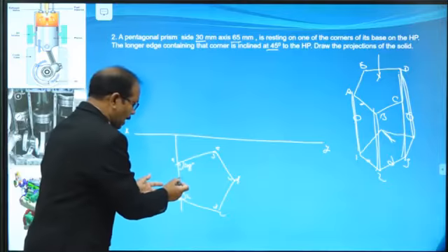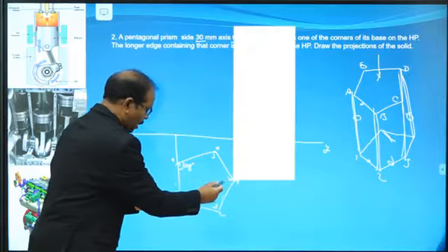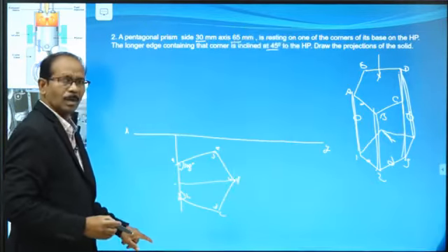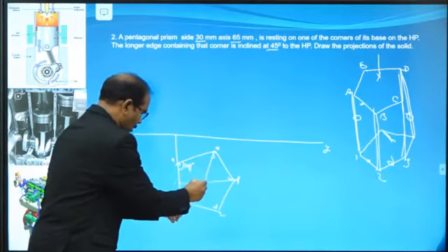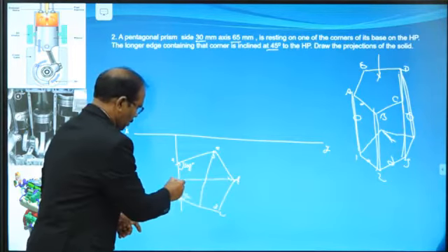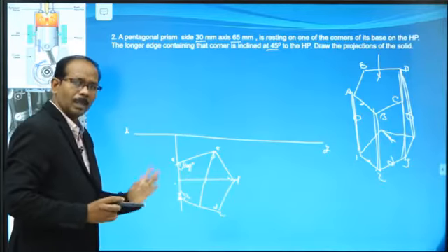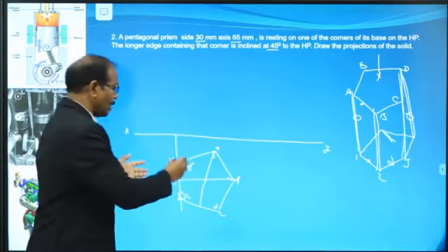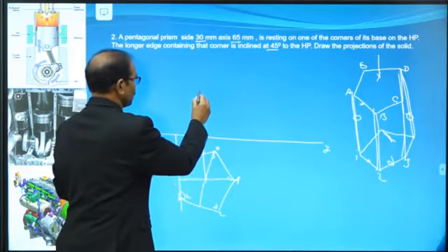Adjacent side, midpoint and opposite corner. Draw a line from the adjacent midpoint to the opposite corner. Then select one more opposite corner and draw. That means this is the midpoint. Now, no, this is the center. Then from that center draw the axis line, the vertical line. So, from here onwards, axis line.